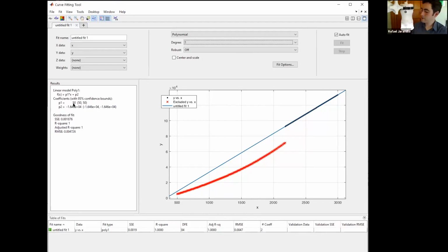I'm gonna look back in my table here, and you can look up the data obviously online. You don't need to have the book handy, although having the book handy is handy. And let's see, does it have the heat capacity of liquid iron? Well, unfortunately, it doesn't have the heat capacity of elements at high temperature, but you'll find numbers between 45 and 50 are typical of liquid metals.